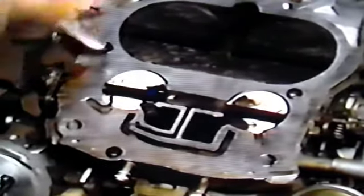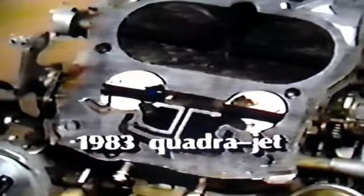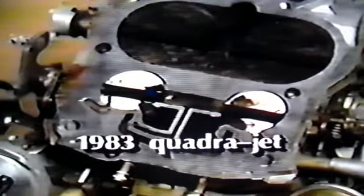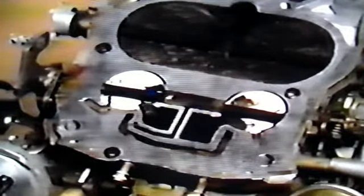The first thing you want to check on the carburetor are the screws holding the throttle plate to the bowl. In the majority of cases, you'll find they're loose and need to be tightened. For purposes of this demonstration, we'll be working with a 1983 Quadrajet carburetor with relatively low mileage, which means it will only require a routine setup and calibration. If this carb had quite a few miles on it, we'd probably have to rebuild it as we went along.